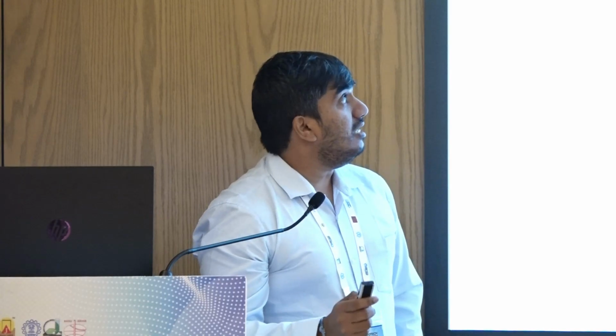Now we are going to see how the variation is with the 1 day sample. As you can see, the behavior is totally different when the sample is cured for just 1 day with the curing stress. Initially, there is a rapid increase in UCS value and stiffness as well. This is actually the consolidation effect. Now we'll see why it's not the self-stress effect. This is the effect of 1 day versus 7 day response.